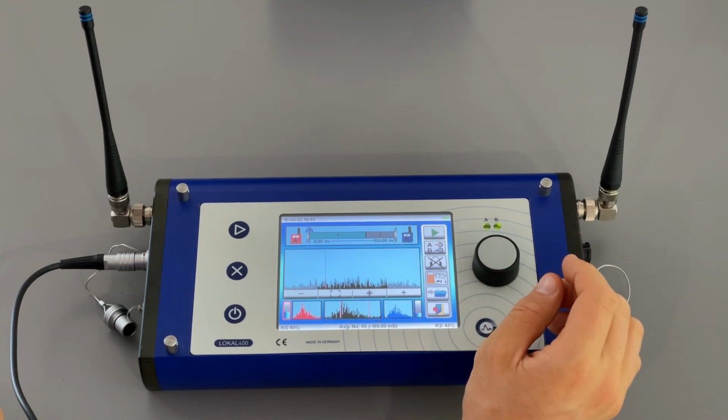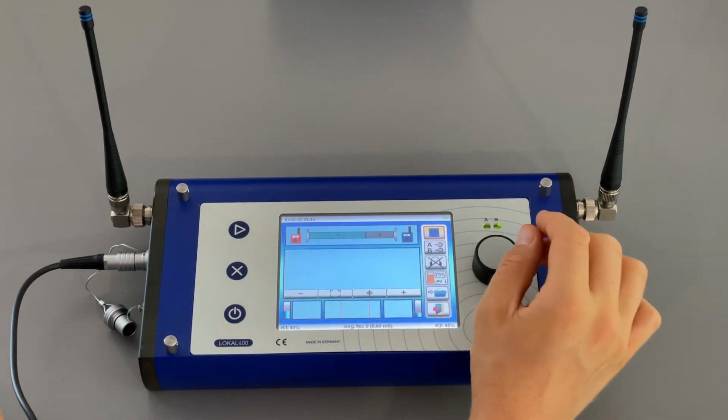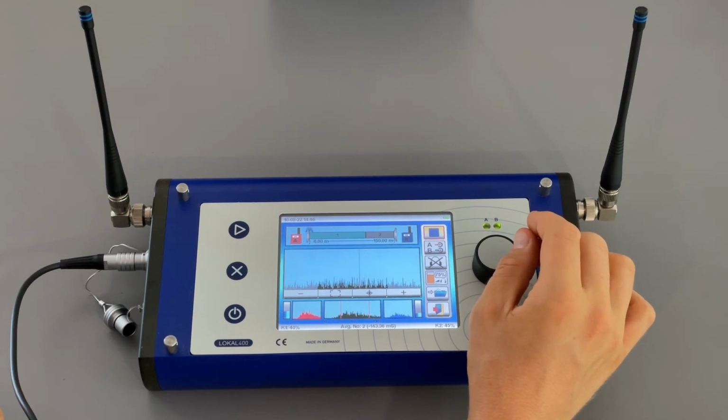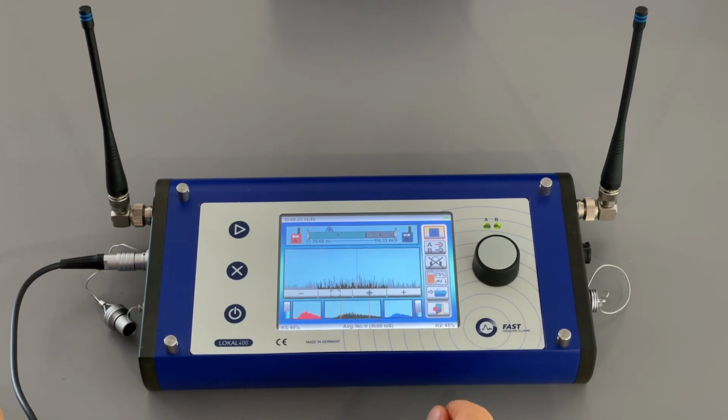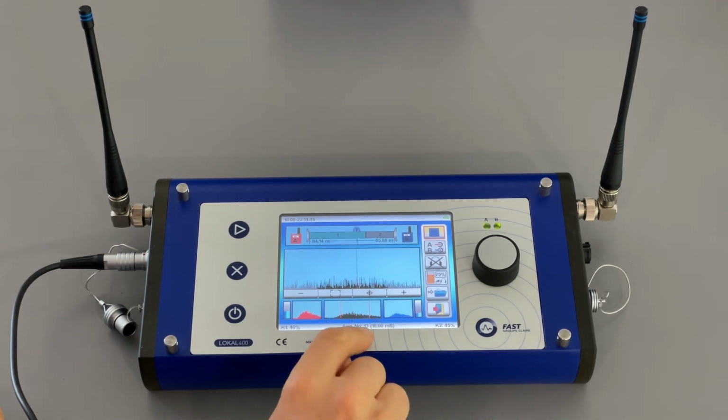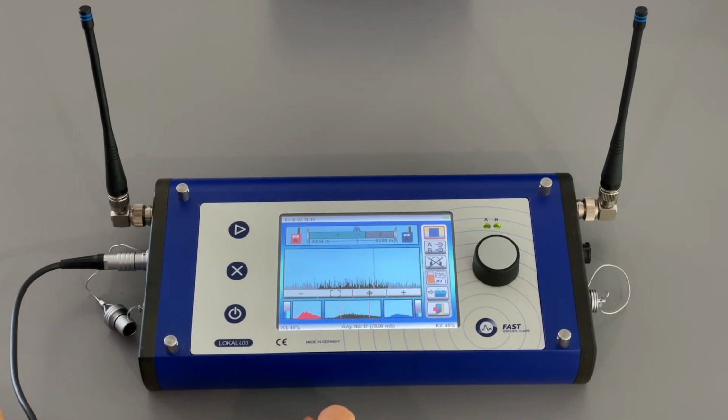when we are ready to start a correlation, we can navigate here and click the start button. Now the correlator starts correlating and taking the measurements. You see down here the number of measurements it has already taken, and other than in the auto mode, it will not stop with 50 measurements. It will continue with measurements until we stop. So it will continue measuring and refining the result. The more samples it has, the more accurate the result will be.